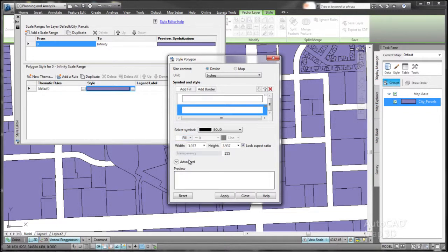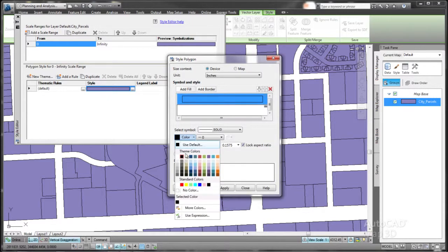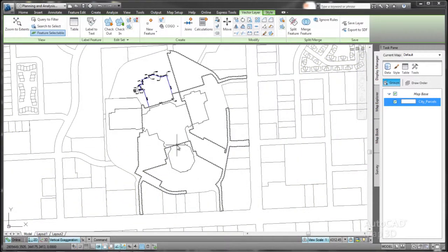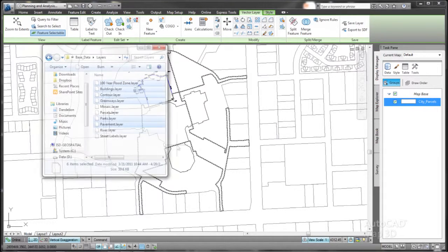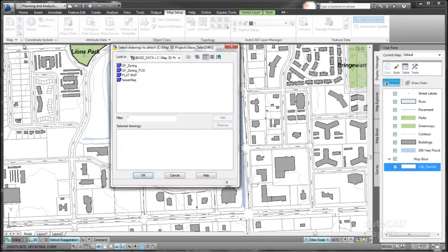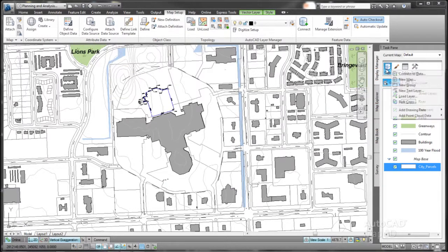information available as an ESRI SHP file from the local assessor's office. After stylizing the parcel, bring in additional GIS data such as hydrology, current surface contours generated from a point cloud captured for this project, flood zones, and both natural and built-up areas around the current project site. This information provides a holistic view of the current site and informs you of factors that might impact expansion development.